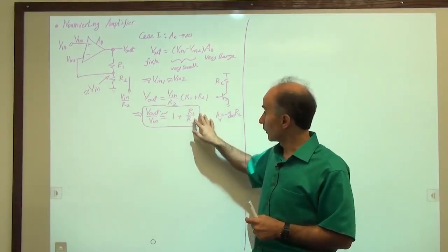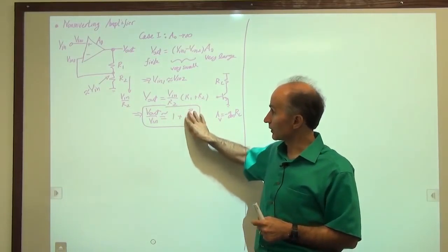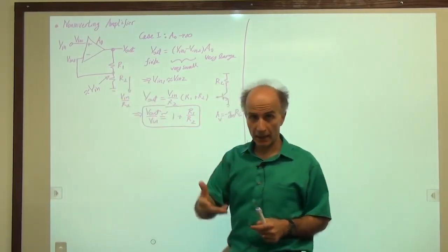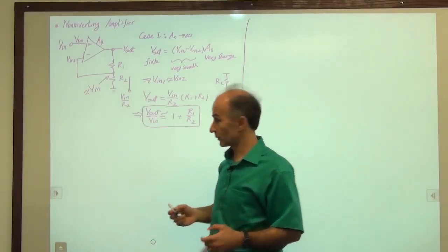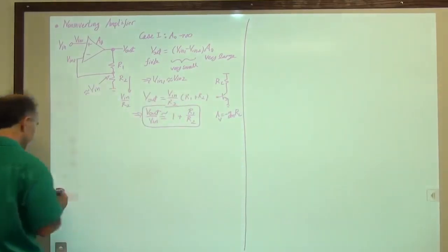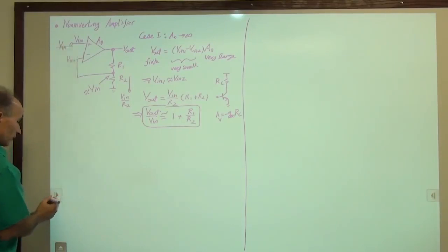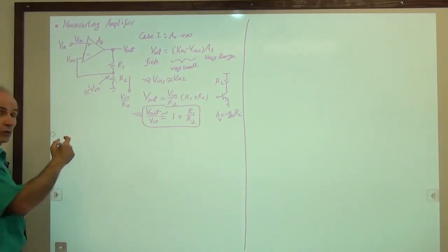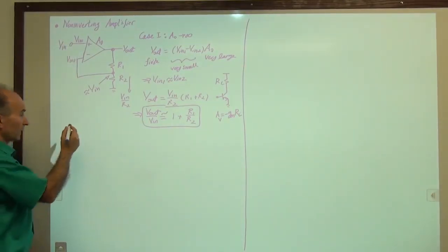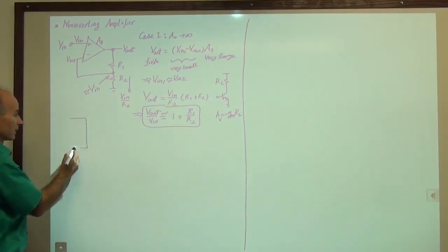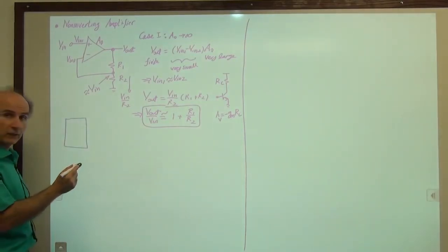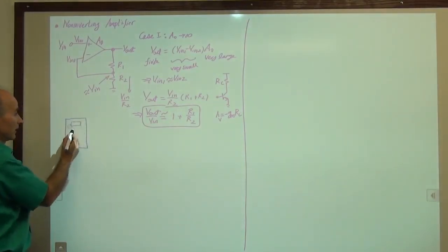In fact, when we want to build this structure here in an integrated circuit, this is how we would do it. We start out with a structure for the resistor. If you look from top to the wafer, the resistor looks like this. It's a rectangle. There's a contact here, there's a contact here, and we have the resistance between these two.